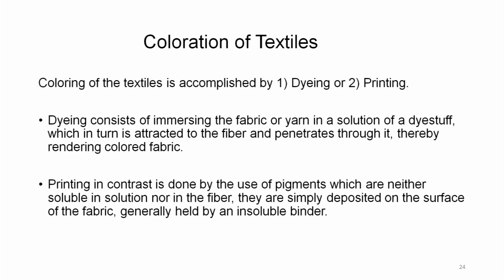Coloration of textile. As we learnt a little while ago, color can be imparted in two ways, by dyeing or printing. Dyeing consists of immersing the fabric or yarn in a solution of dyestuff, which in turn is attracted to the fiber and penetrates through it, thereby rendering colored fabric.